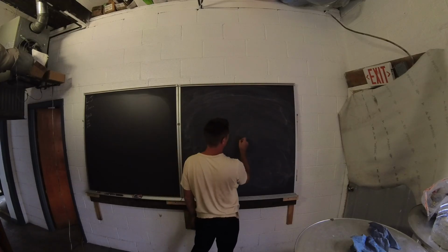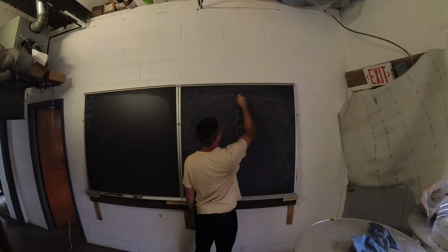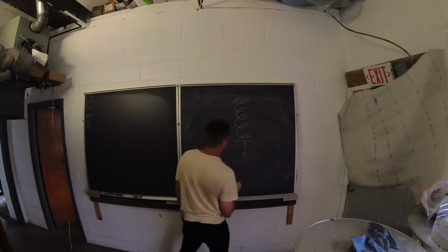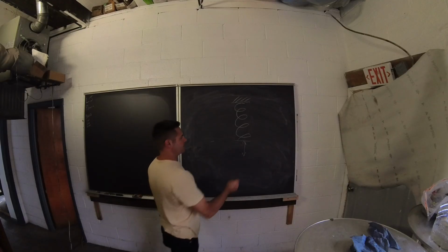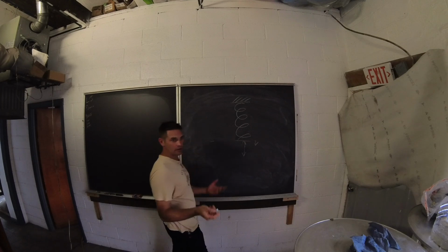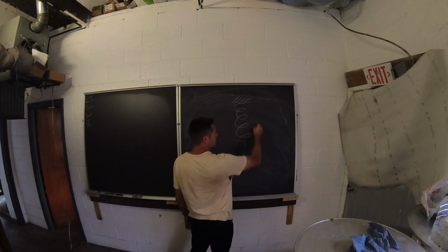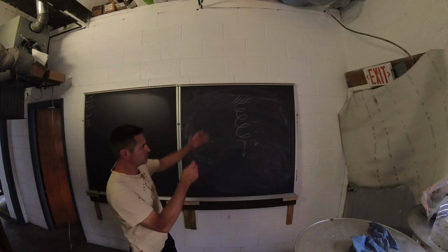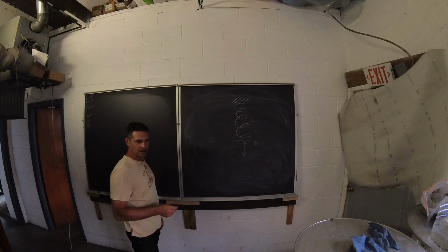So we'll draw a coil spring, right? Here's our coil spring. The top is fixed, the bottom moves up and down. Well, you move the coil spring up, it exerts, we'll say, 10 pounds down initially. You move it up a little more. In this case, it's a straight rate spring, so it's 10 pounds for every inch. You go up another inch, it's another 10 pounds, so it takes 20 pounds to move 2 inches, 10 pounds to move 1 inch. Not such a hard concept.